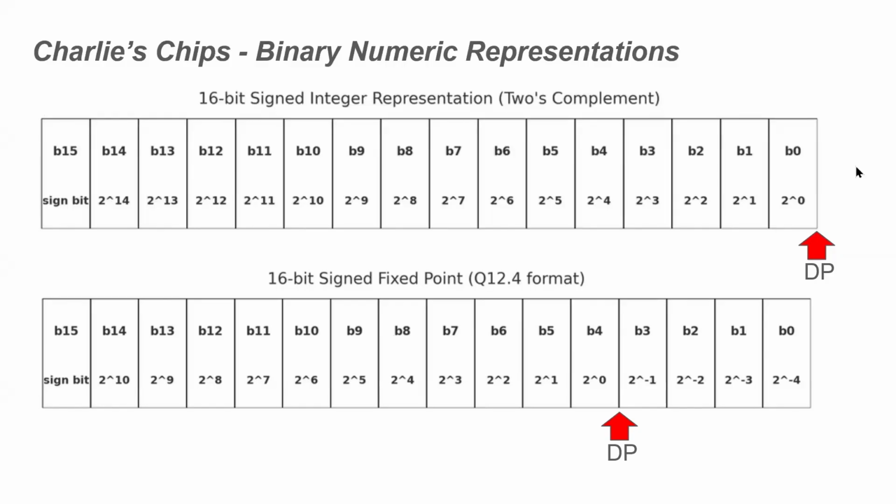And almost the same for our multiplication and division. We have to do a little bit of pre-processing for our division, and a little bit of post-processing for our multiplication, but we still are using the same code for our 16-bit integer as we are using for our 16-bit fixed point. Now, while that's true, we can use the same code.